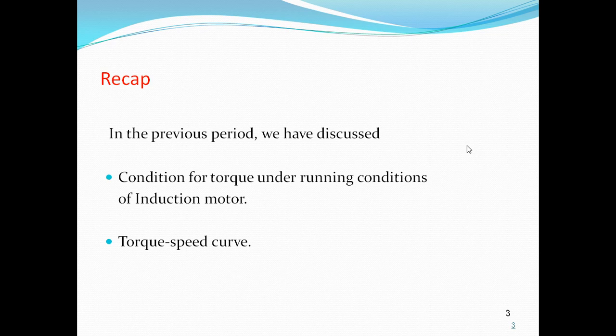Starting torque should be more than the torque required by the load connected to the motor shaft, to enable the motor to start with the load. The magnitude of the starting torque and maximum torque depends upon the rotor resistance.